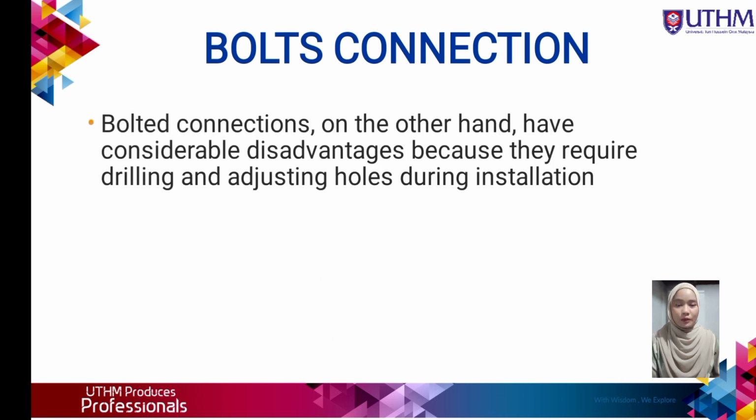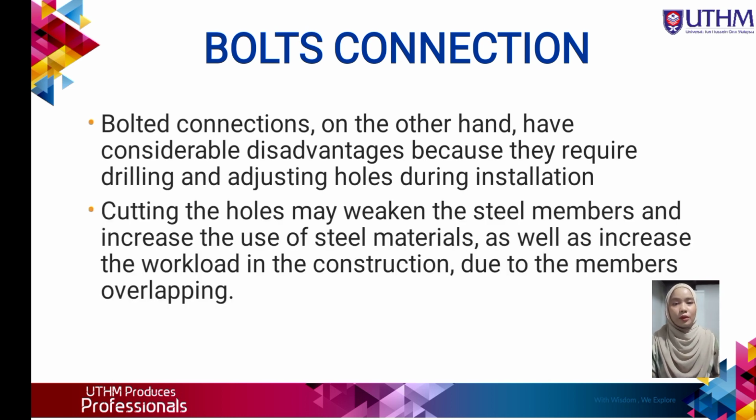Bolted connections, on the other hand, have considerable disadvantages, because they require drilling and adjusting holes during installation. Cutting the holes may weaken the steel members and increase the use of steel material, as well as increase the workload in construction due to the members overlapping.